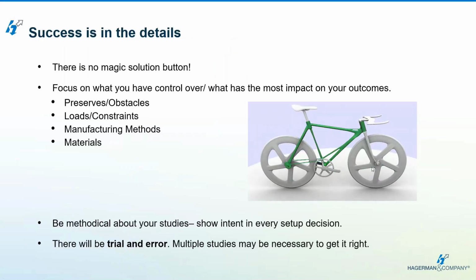So when we're thinking about generative design, once we start doing this, there is some information that we have to remember for generative design. And I'm going to show an actual demo of creating an easy bracket on this webinar here. So first thing we have to remember is there's no magic solution button. So we want to focus on what we have control over: our preserves, our obstacles, the geometry that's there, the geometry that we want it to grow around or create around, and things that might attach to it. Also, we want to control the loads and constraints.